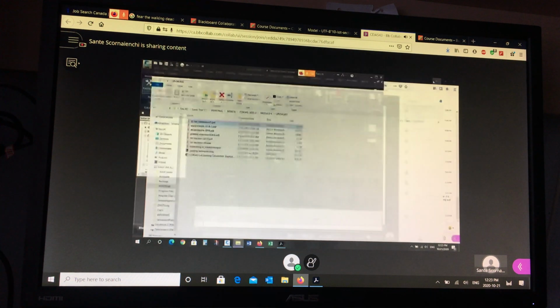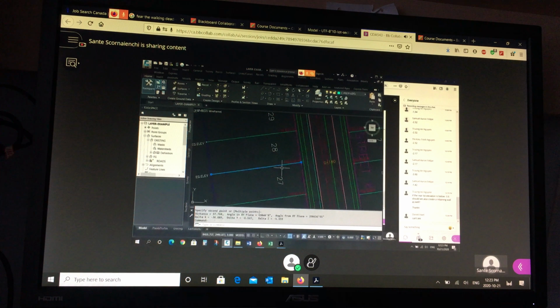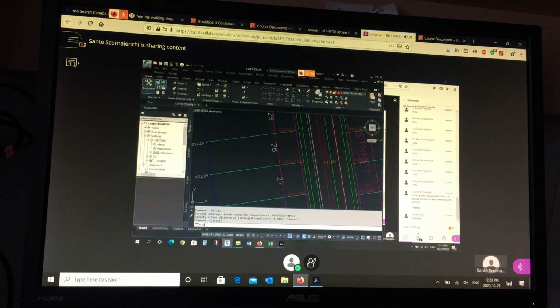For that one there's going to be a number at the front of the house, a number at the back of the house. Let me just show you some offsets. Offset 8 meters from the front. That's where the building starts. Offset 12 meters. There's the back of the house. Offset 7.5 meters. There's your usable backyard.